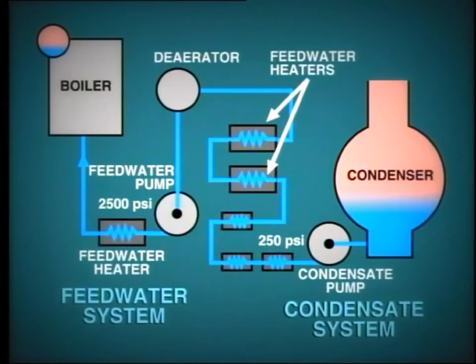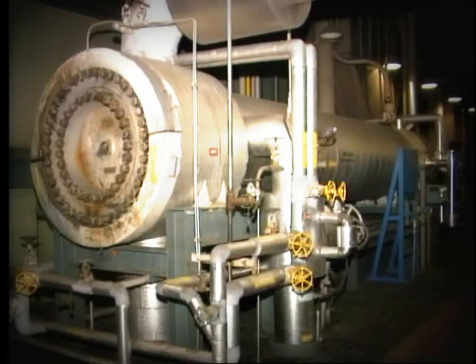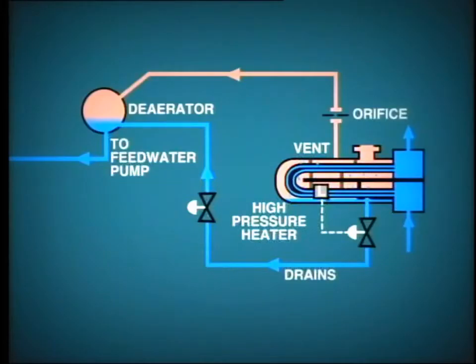heater is functioning correctly. In the system shown here, we have another closed heater on the high-pressure feedwater side of the system. In this case, operation of the heater is similar to the LP heaters. The main difference is that the heat exchanger must be built more ruggedly to withstand the much higher pressures on both the feedwater side and the extraction steam side. As before, care must be taken with venting and drainage of condensate from the shell. However, in the case of this high-pressure heater, both the vent and heater drains are piped to the de-aerator, which of course operates at lower pressure.